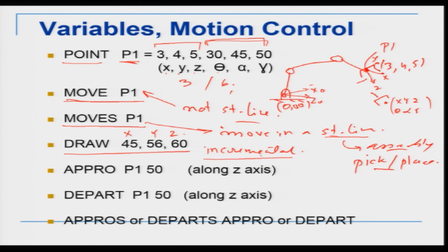So, wherever it has reached, for example, the robot has come to this point, just for an example, okay, but I wanted it to come to this point. So, what I will say is that it has reached this point, but now I want it to come to this point. So, I want to change a little bit of the coordinate here in the x, y and z directions with respect to this. So, this is my x, y and z. So, this change I can make by simply saying, let us call it del x, del y and del z. Okay. So, this is an incremental change from the last position, and these are very small units of motion in the x, y and z directions correspondingly. So, draw is basically used to make a correction on a command.